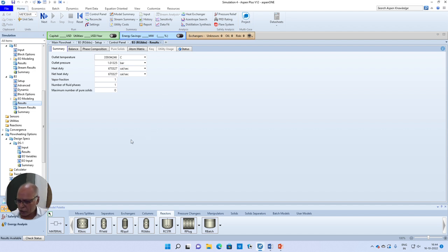So with this, you now should be in a position to handle even multi-reaction equilibria. Remember, these two reactor models will be capable of handling only reactions reaching equilibrium. Remember, when you are talking about reversible reactions at equilibrium, we don't need the kinetic information, right? So even the stoichiometric reactor model and these two reactor models don't require the stoichiometry. So with this, I would like to stop my presentation.